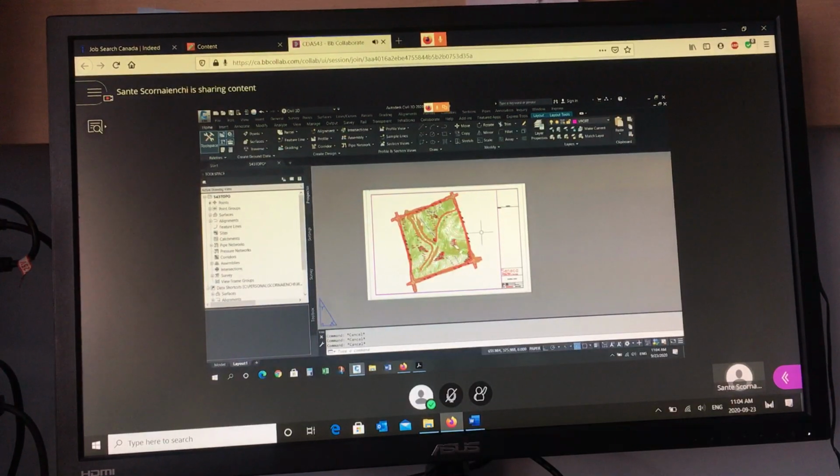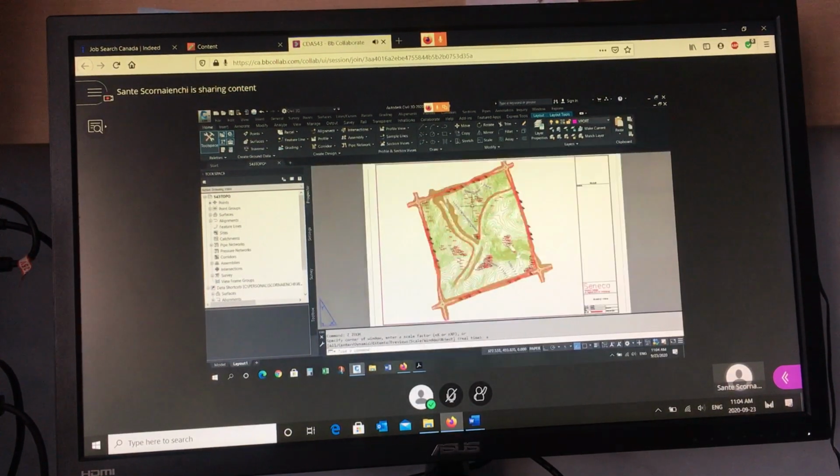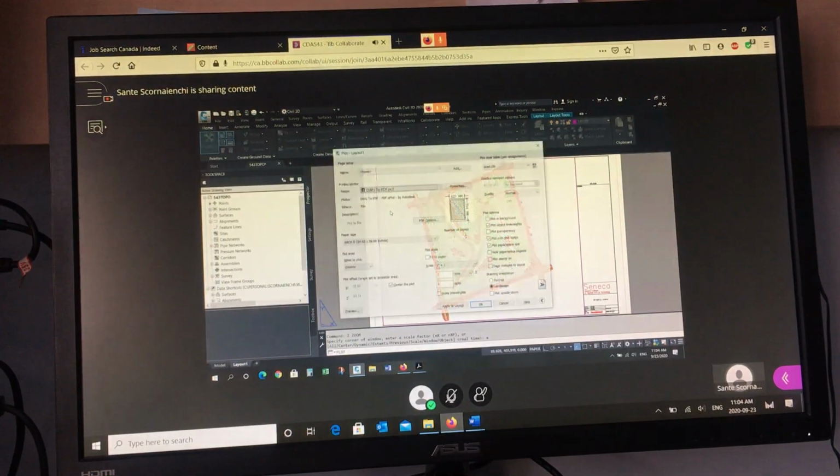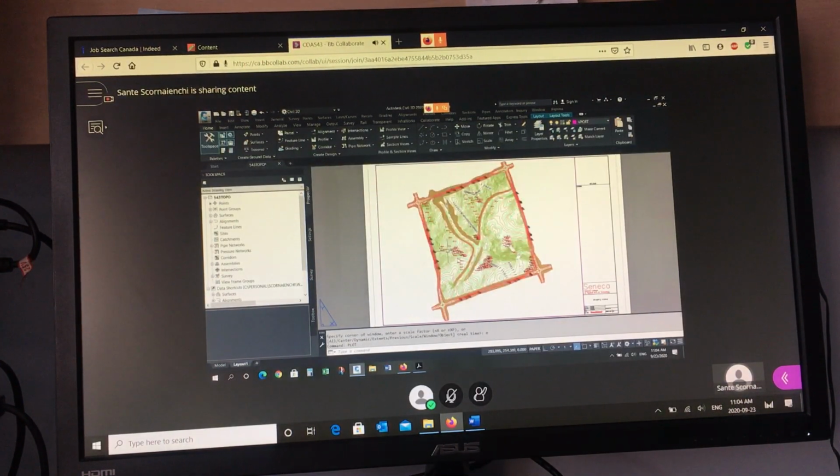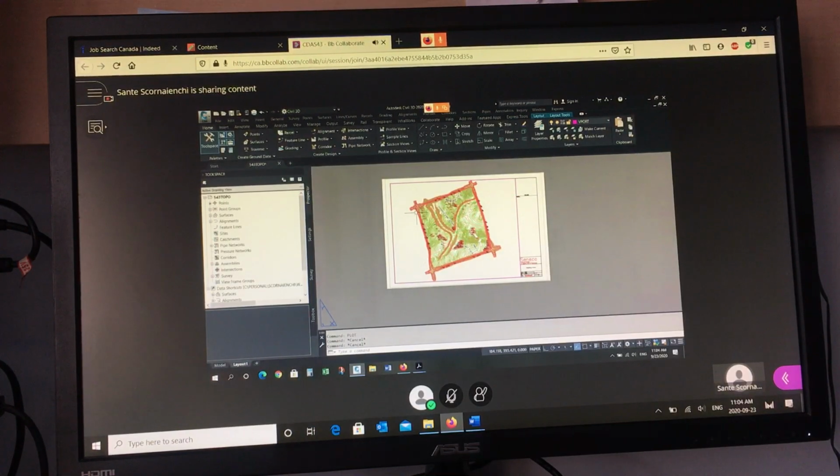And now the scale. A couple of ways of establishing scale. Okay, the first thing you want to do is ask what's an appropriate scale for this size object? Well, the paper scale is always going to be 1:1. We're always going to plot at 1 millimeter equals 1 unit, which on paper is 1 to 1,000. However, we can manage the size of the object. We can change the zoom factor and change the scale of the drawing without having to change the plotting scale. So if anybody opens this drawing, they just plot it. It's always 1:1. But whoever set up the drawing can change the zoom factor and have different scales on the drawing. Okay? In this case here, we will use a 1 to 1,000 scale.